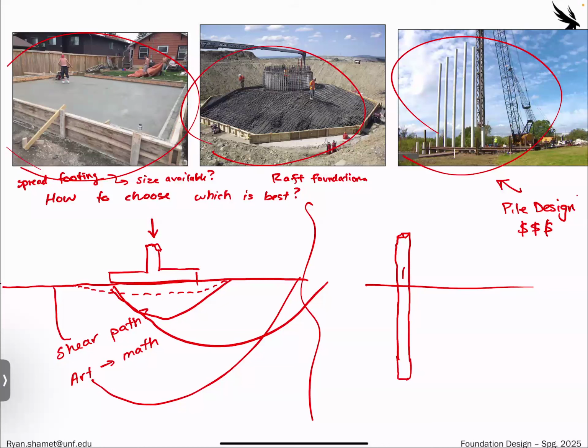The soil conditions for the embankment, especially on the north side, the Green Cove side, is really, really poor. It's just that St. Johns River is super old. It's just been dumping organics for a really long time. And it's such a large loading on the embankment that they're doing these huge piles. So WSP is the geotech, and we've been talking about hopefully setting up something where we can actually go and see the pile driving of that.